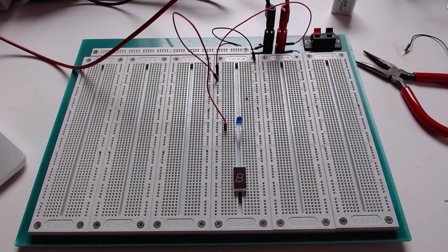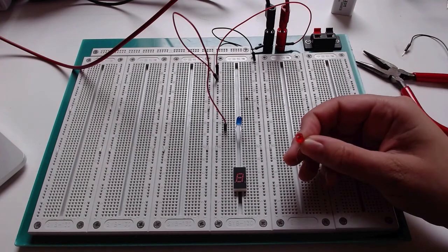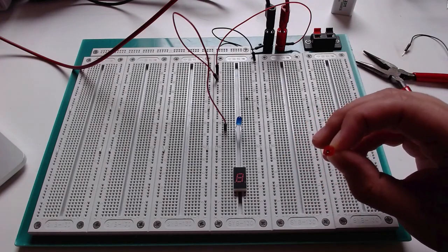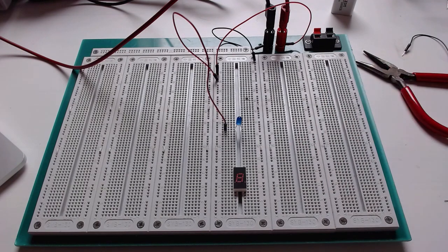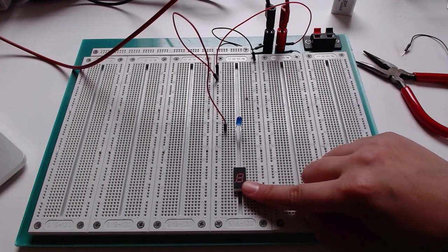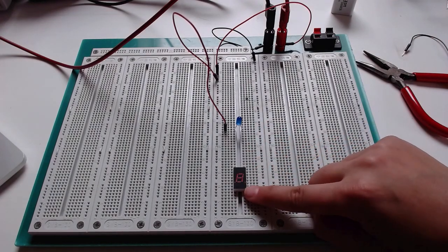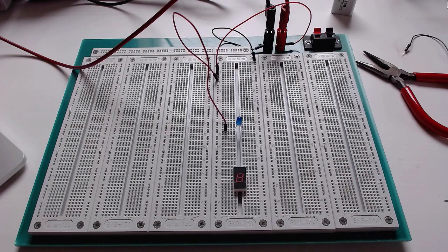So what happens if we use a resistor that's too small? Well, if we use a resistor that's too small, we wind up with something like this. Okay, so we want to avoid that. So there's going to be a minimum value for the current limiting resistor. If we look at the data sheet for our device, whether it be an LED or a segmented display, there are two things that we are interested in on that data sheet. The first thing is the forward voltage drop. The second thing is the maximum forward current.